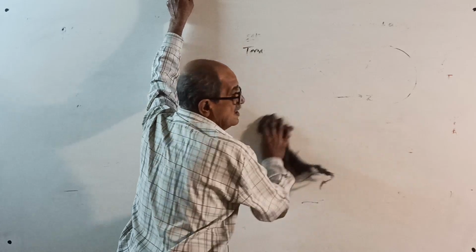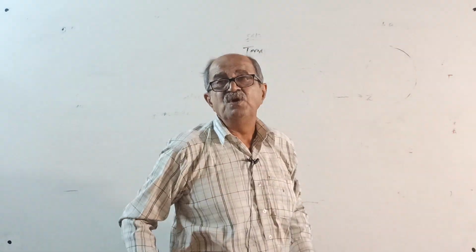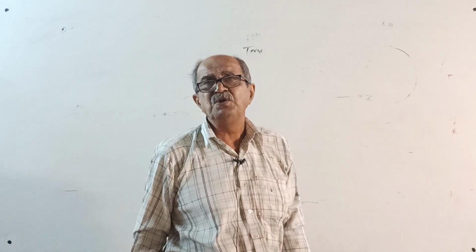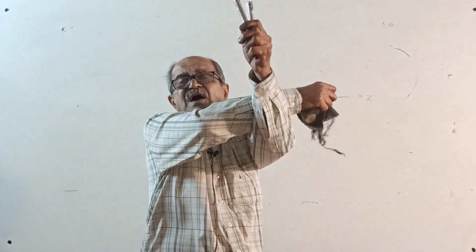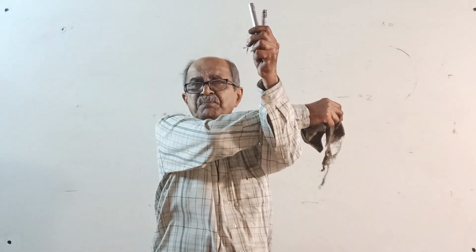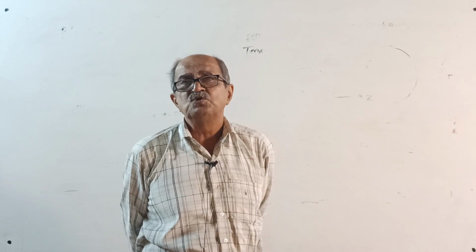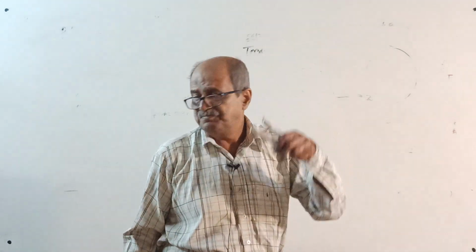Therefore, in the summary I will tell you: in any examination, if they ask for polar moment of inertia, what do you do? You find the moment of inertia about two mutually perpendicular axes lying in the plane, and then add those two. That is the perpendicular axis theorem. I will explain later.